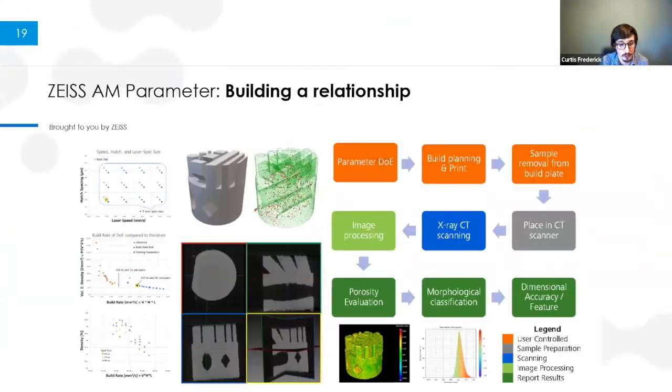To create your process parameters and scale up your machine or your process to production scale, you need to use process parameters that increase the build rate. We were moving to an SLM 500, so we had a 650 watt laser, and that allowed us to increase to 90 micron lasers. And you can see there in one of the graphs that we doubled or tripled the production speed depending on how much porosity you're allowing. So our DOE really pushed the boundary of production speed.